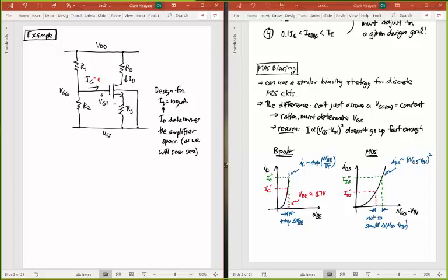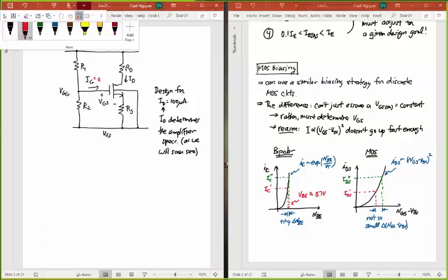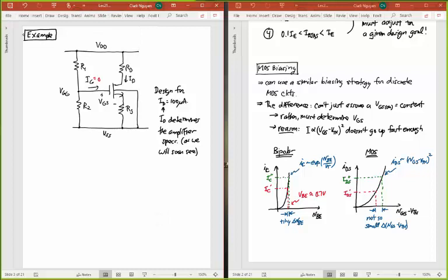So how do I go about doing this problem? Well, naturally you want to apply KVL and that sort of thing, Kirchhoff's laws, to analyze the circuit. And this really just boils down to circuit analysis at this point. So let's first do things that are very quick. I have no current going to this gate. So this really truly is a voltage divider with an open circuit at the output.